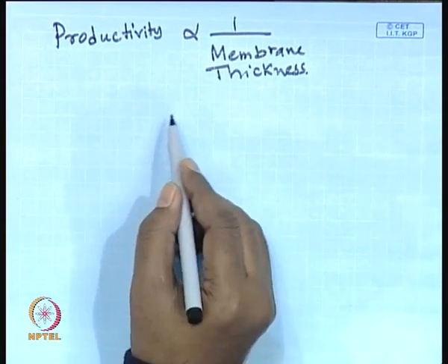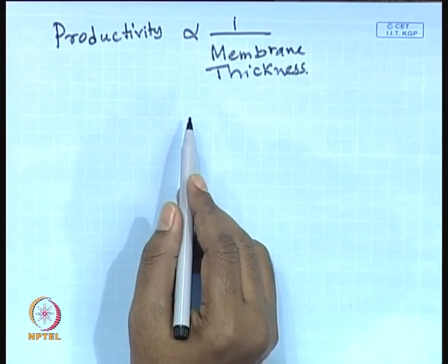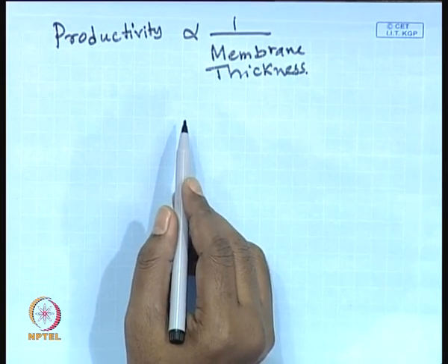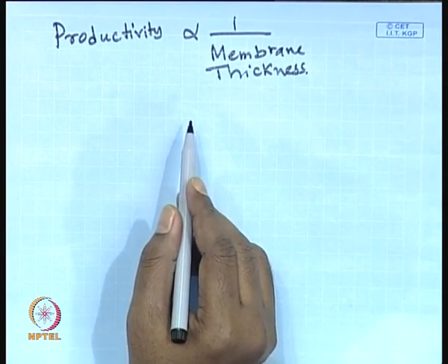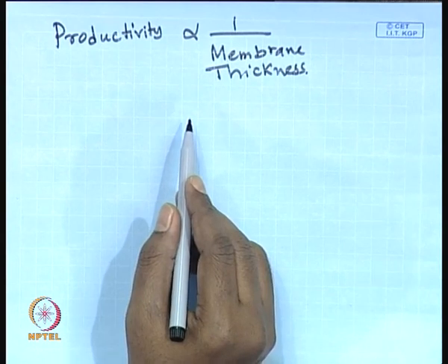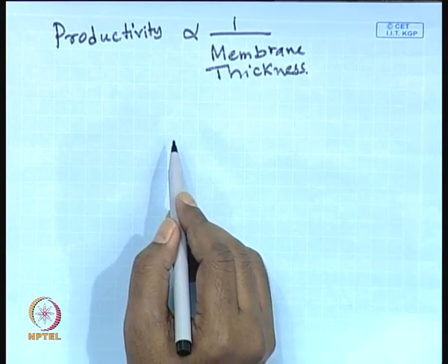First, on a non-woven polyester fabric, you put a coating of, let us say, polyacrylonitrile or polysulfone, something like that. These polymers will be cast as a film on the polyester fabric with, let us say, higher pore size. Then you cast another film of, let us say, cellulose acetate or polyamide over it. Basically that will create a skin over the higher pore sized polymer support.